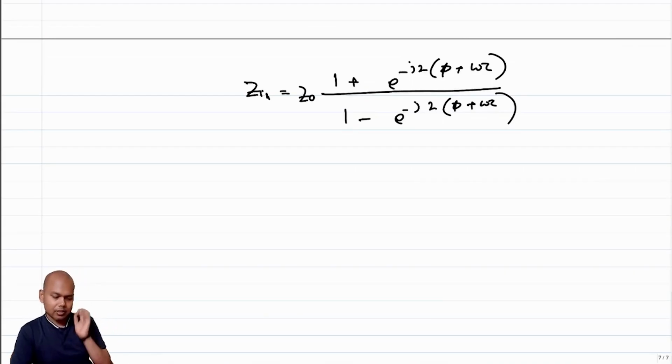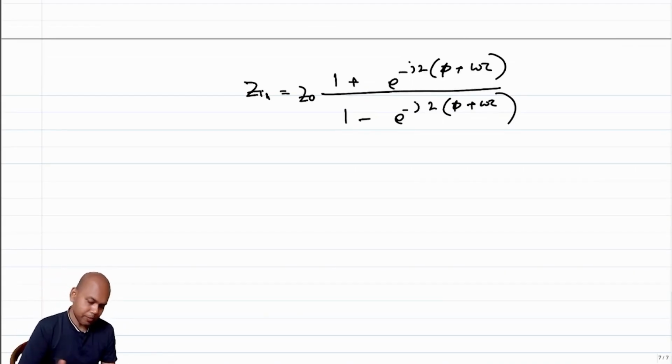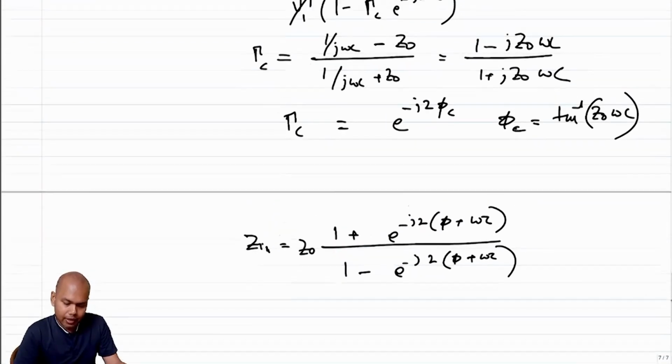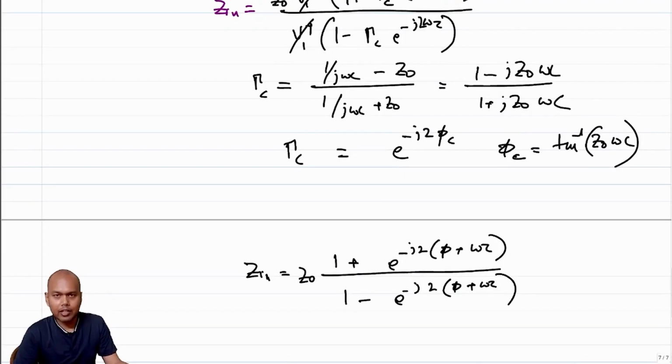So what is this telling us? This impedance can be anything. Depending upon what ωτ plus φ is, it can be 0, it can be infinite, it can even be real, at different frequencies and for different lengths of the transmission lines. So just observing Zin when you have a long line associated with a long delay is useless. That we already knew, but this gives you a mathematical framework for understanding why this is happening.